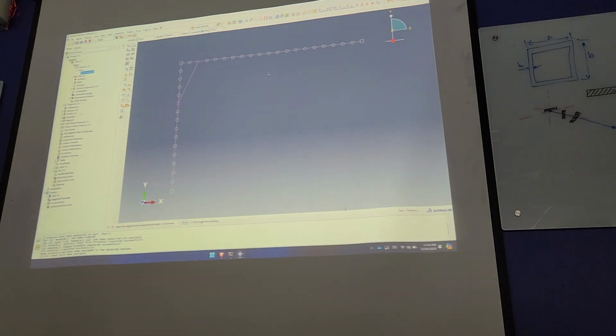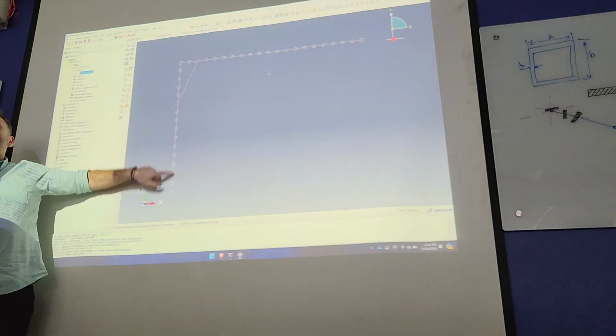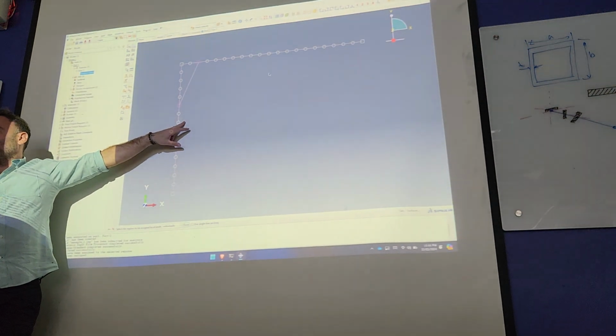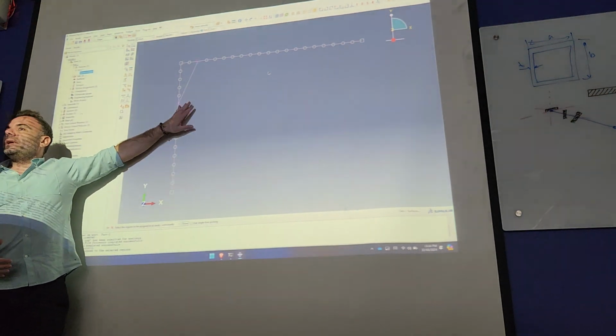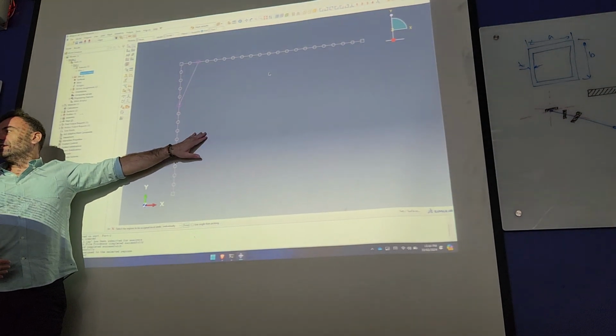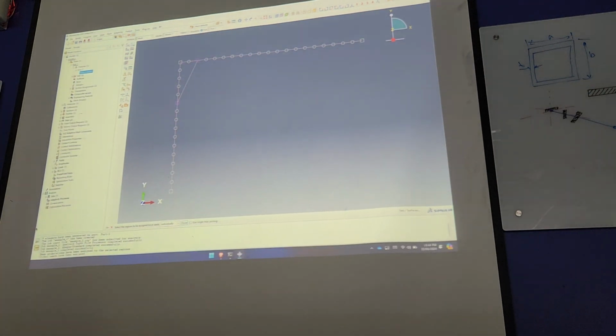But that doesn't fix the problem of the beam. I'm saying this just for the future: if you got something similar, and if these are okay, and then you need to change to truss, that's how you would do it. You would create a global seed for everything, and then you pick where your truss is and assign a so-called local seed. Yeah? So we go back to what I had, 500. Now, we are not done here yet.